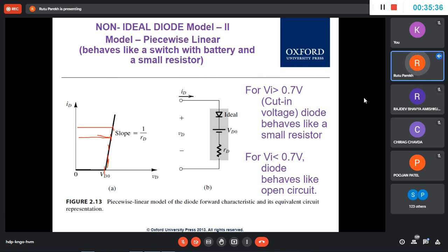So if you have 0.7, then 0.71, you will have, you know, this much current. 0.72, 0.74, you will have this much current. 0.75 volt, you will have this much current. So it is in points only, little difference. But the current will change. Okay, and the ratio of this to this is R. You will see what is changing here is the change in the R. The resistance of the diode material is changing with respect to voltage, and so your current is changing. Do you understand? So this is known as dynamic R.